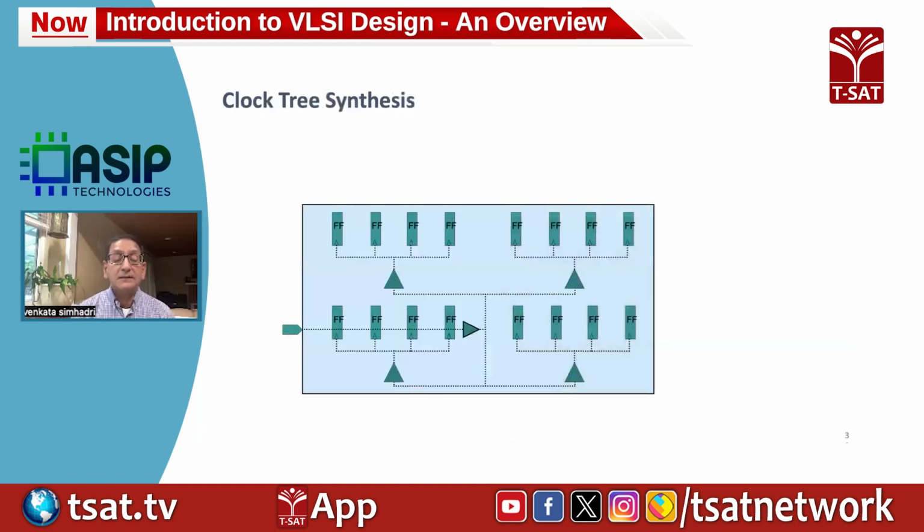And the next step in the physical design is to build clock trees. So let's say you have a clock signal coming from the periphery of the chip, and it's driving thousands or sometimes millions of flip-flops in the design.